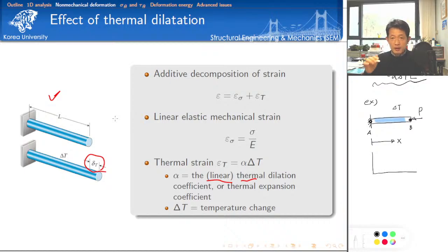That's why we can consider a straight line as the displacement distribution. So make sure that node A is fixed. If you plot the displacement distribution, node A is fixed, and here this is the x coordinate, and we call this length L, with point A and point B. Then we have to consider a certain nodal displacement, UB. The distribution of displacement is straight.